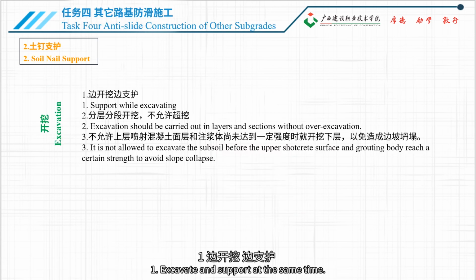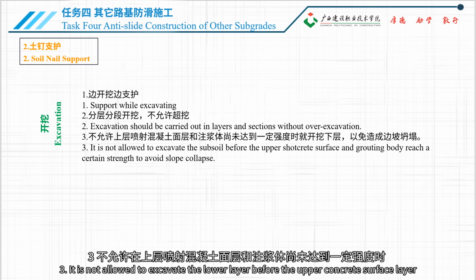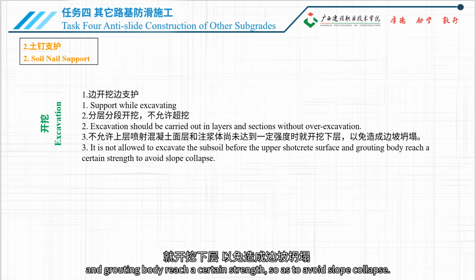Excavation. 1. Excavate and support at the same time. 2. Excavation shall be carried out in layers and sections, avoiding over-excavation. 3. It is not allowed to excavate the lower layer before the upper concrete surface layer and grouting body reach a certain strength, so as to avoid slope collapse.